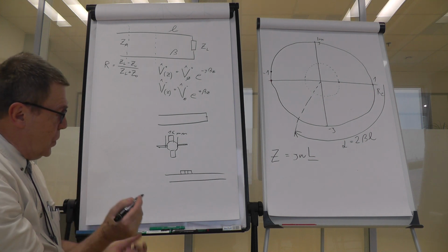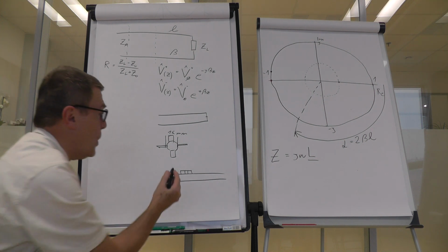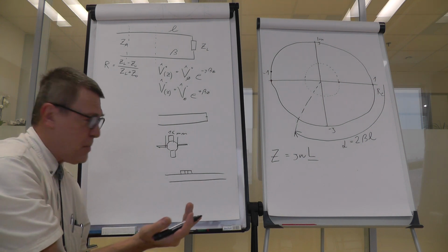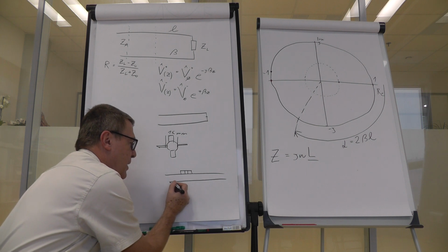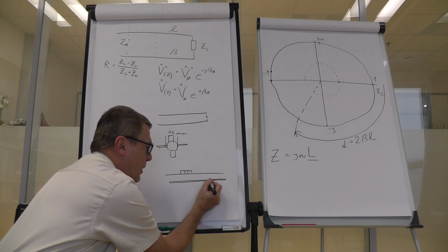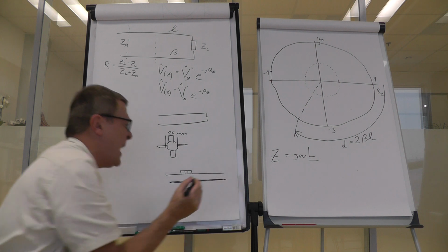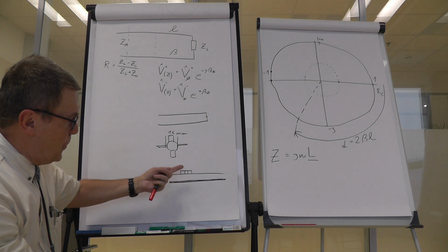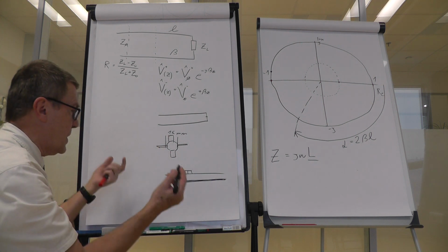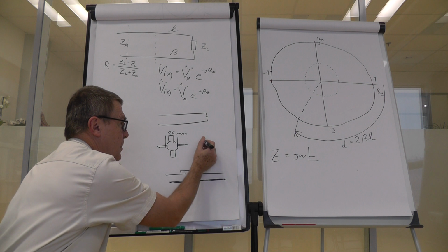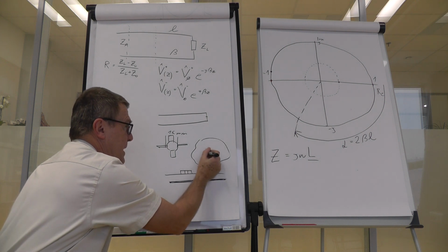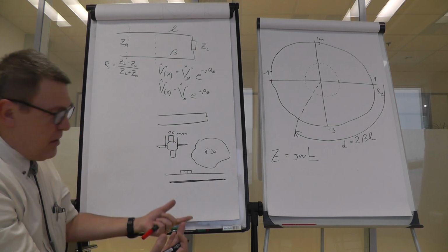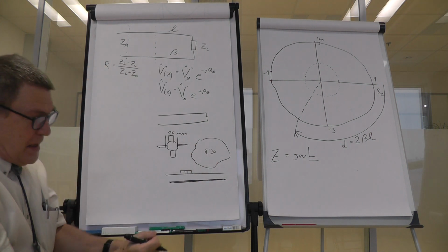And you want to connect it somehow. Mostly this is used in microstrip circuits, where you have a ground on one whole side of the board, and now you have to connect the transistor down somehow. The simplest way is to drill 2 holes and put those emitters that should be grounded just downside, so you bend it.